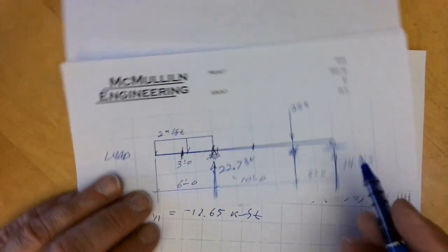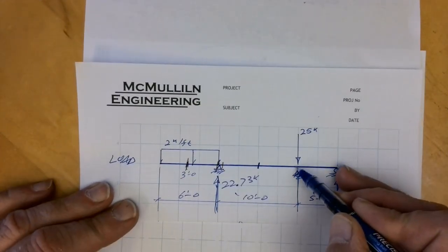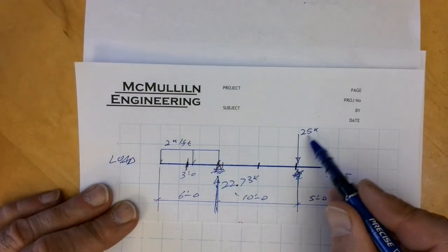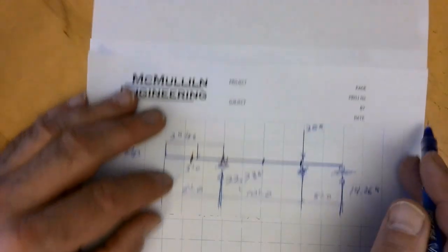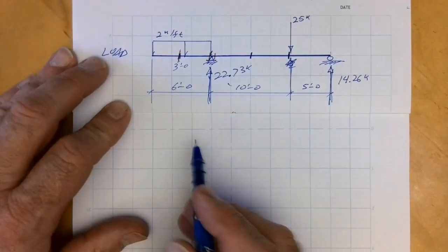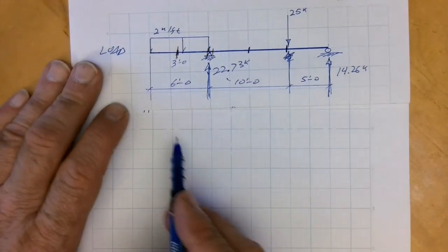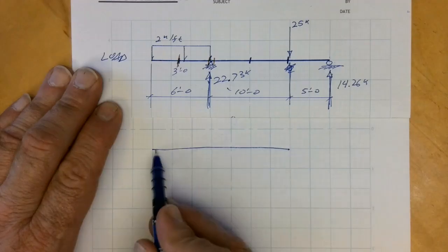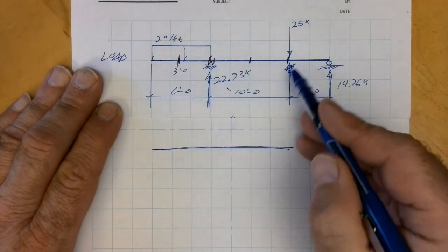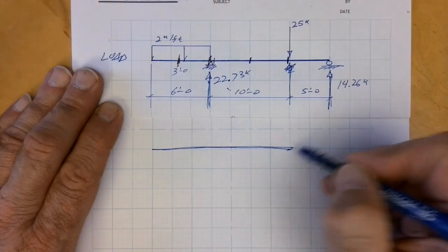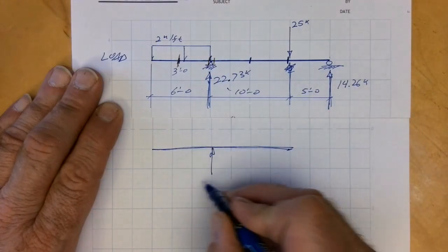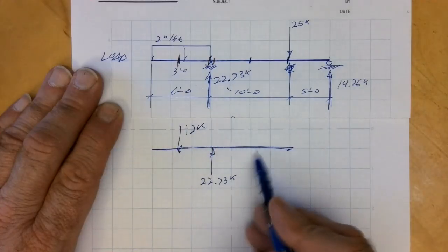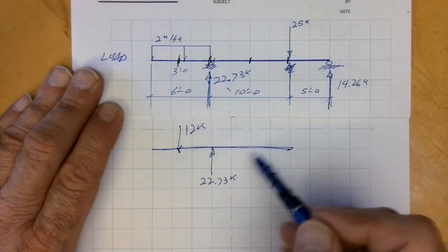All right, let's keep going. So let's do this. Do a point right here, 1/1000 of an inch left of 25 kips. So let's draw our new free body diagram. And this is starting to get a little burdensome because we're getting further to the right, but we can handle it. Because I'm to the left of this guy, it doesn't show up in my free body diagram yet. So I have this. I have 12 kips. The stuff we just did right here doesn't matter because that's internal.